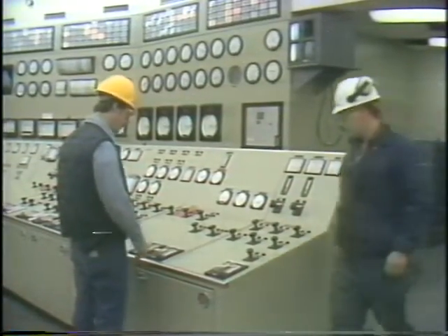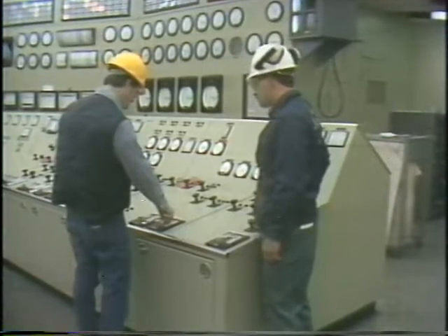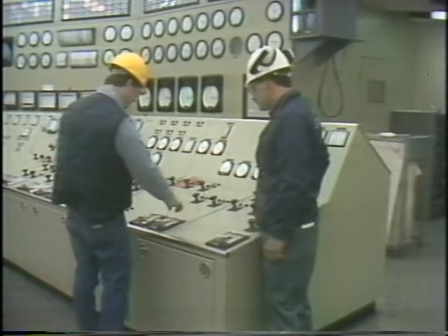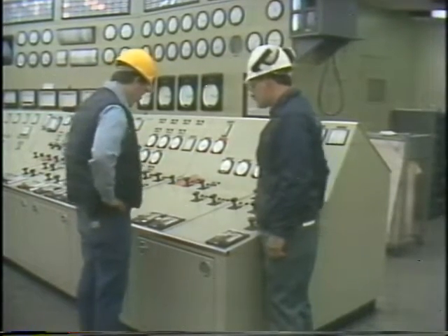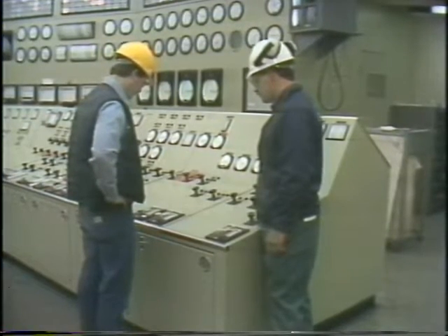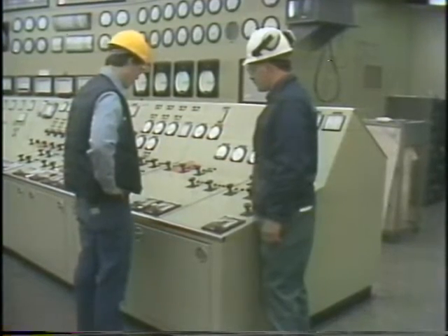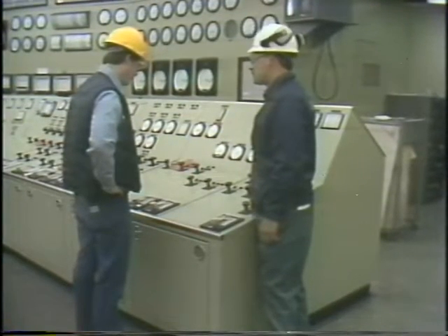Now, another way to diagnose a problem is to place the system in manual and compare the way the system operates with the way it operates in automatic. You can do this by checking the system's visual indications, such as looking at gauges and recorders and so on. Then, if possible, you may want to duplicate the conditions under which the problem occurred to see what happened.